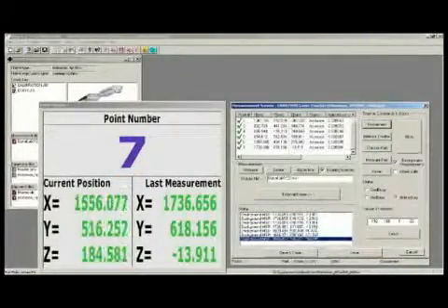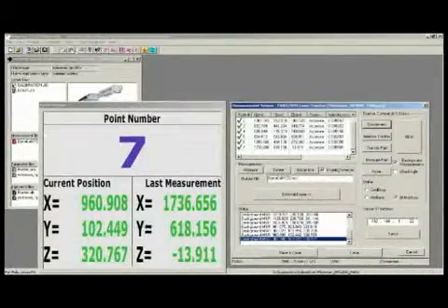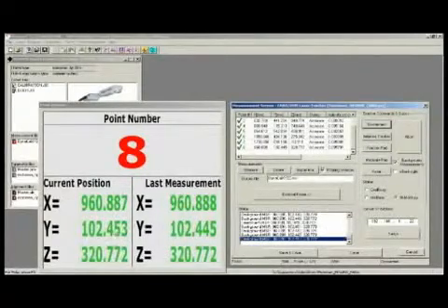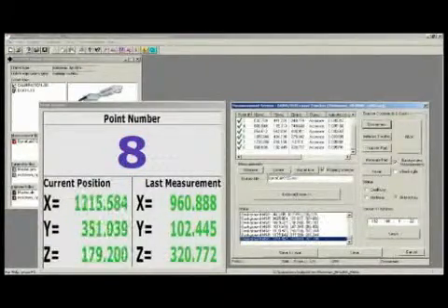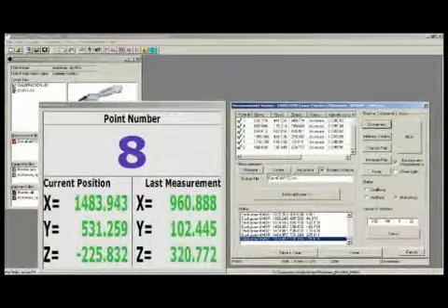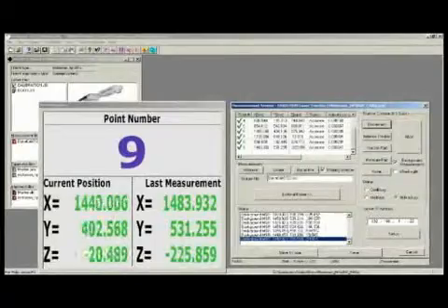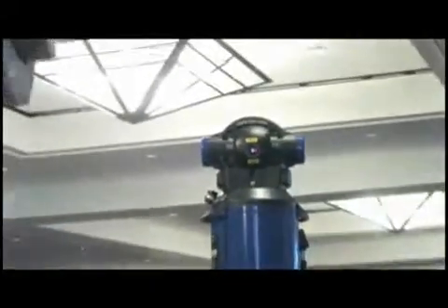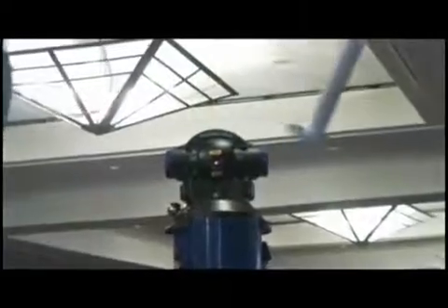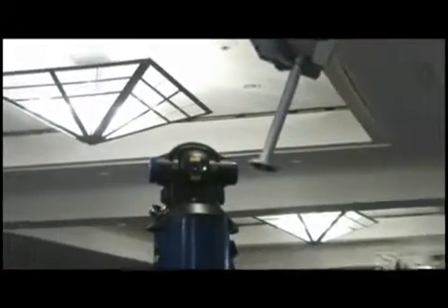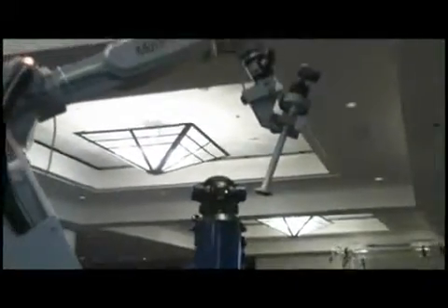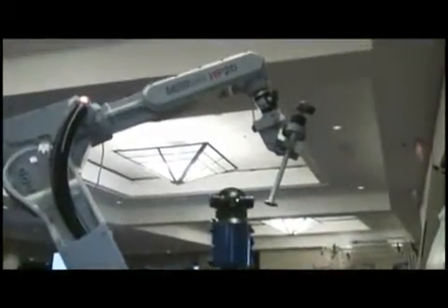In this step of the process, this is the identification step, and you can see in our software we have an interface with the FARO laser tracker. In fact, the Dynalog software can control the laser tracker directly. Dynalog developed the interface with the FARO tracker using the software developers kit provided by FARO. And so with a single application, the Dynalog application, you can connect directly through an Ethernet connection to the laser tracker and take these measurements into our software. And so there's no need for any data transfer later on. It makes the process very convenient and easy to use.